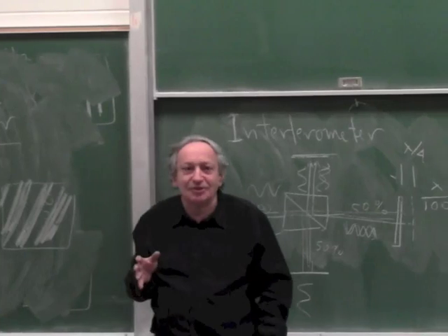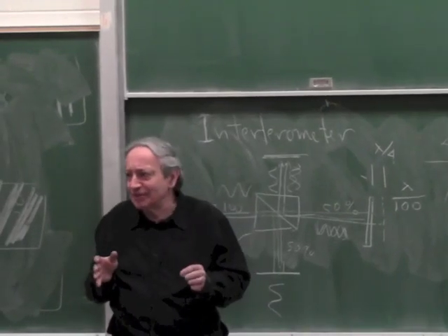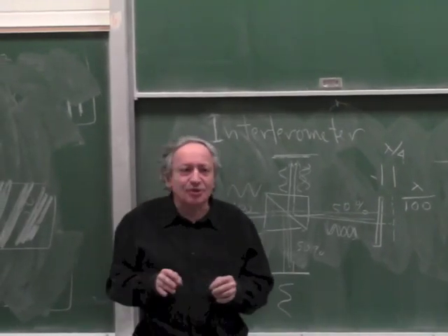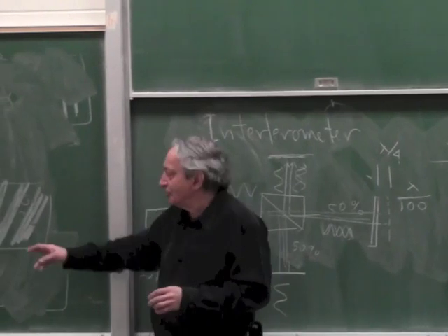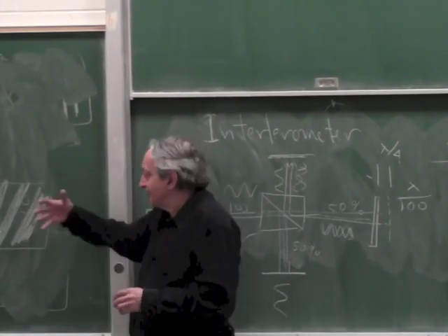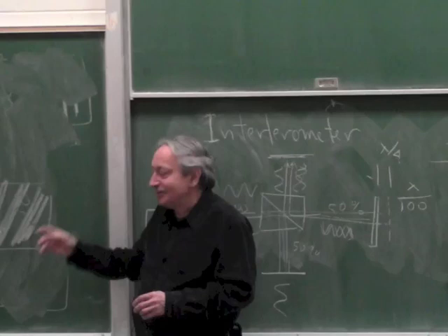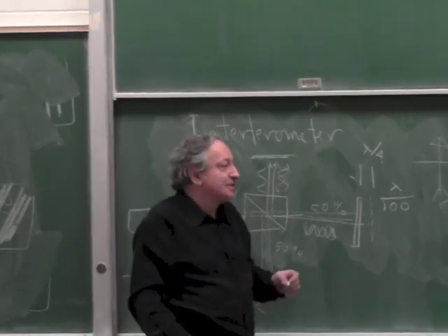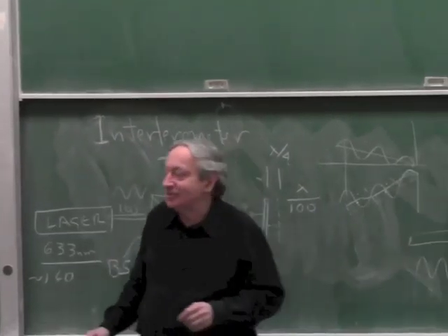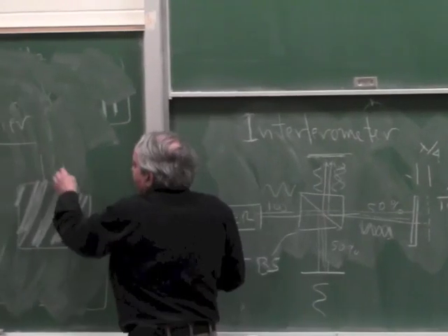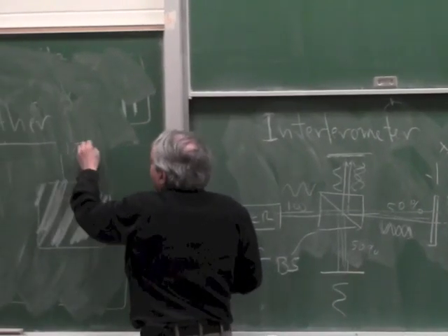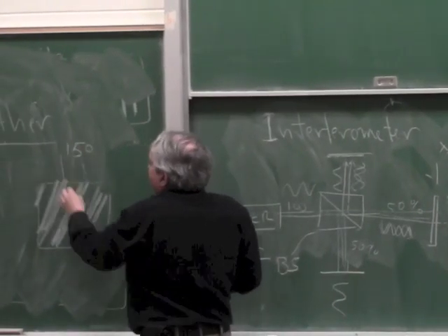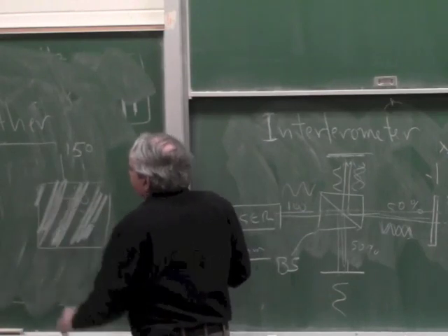Because with an interferometer you're not interested in very fast measurements, so the camera has enough time. So most modern interferometers actually don't put it through a split detector, but put it straight onto a CCD sensor. And you analyze it with software. And those ones can go to a nanometer. Because imagine if a full movement is 150 nanometer, a camera can easily analyze 1% of that.